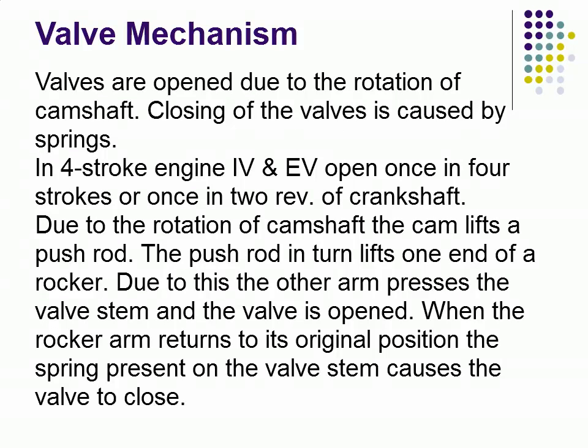Now we shall learn about the valve mechanism. Valves are opened due to rotation of camshaft. Closing of valves is caused by springs. In 4-stroke engine, inlet valve and exhaust valve open once in 4 strokes or once in 2 revolutions of crankshaft.